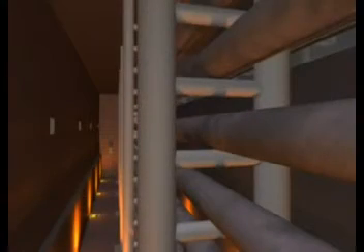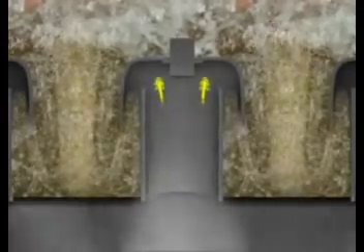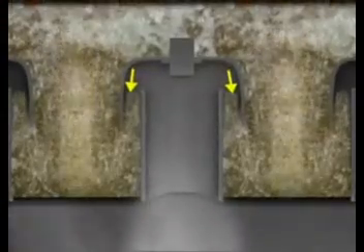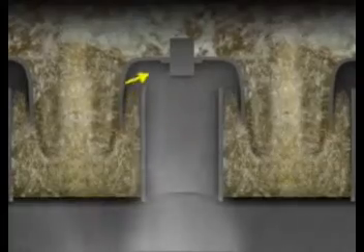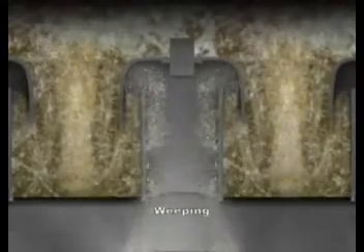Effectiveness of the distillation process greatly depends on proper reboiler operation. If, for example, the reboiler does not provide sufficient heat, there will not be enough vapor rate. If the rate is too low for the design of the tray, the vapor can't force its way through the liquid, lowering the liquid level. The fluid could even enter the riser pipe and trickle down to the tray below. This is referred to as weeping.